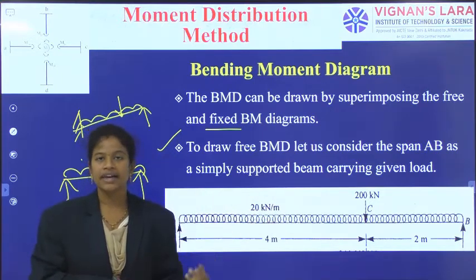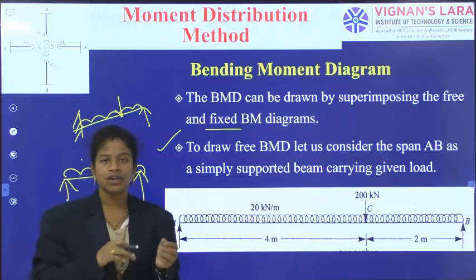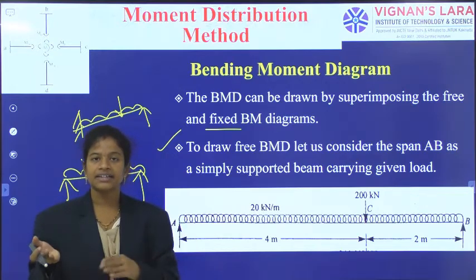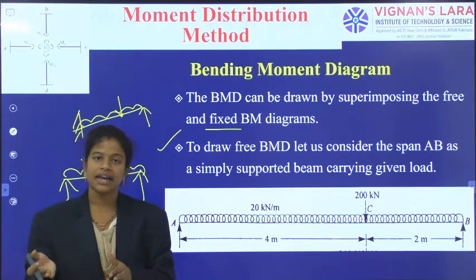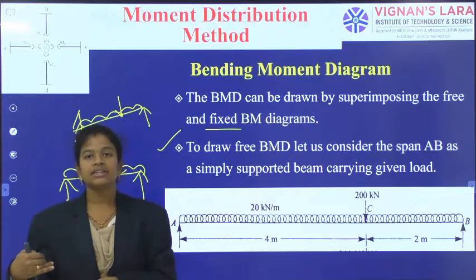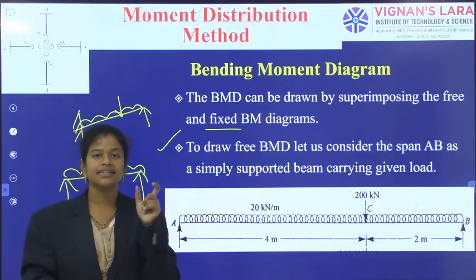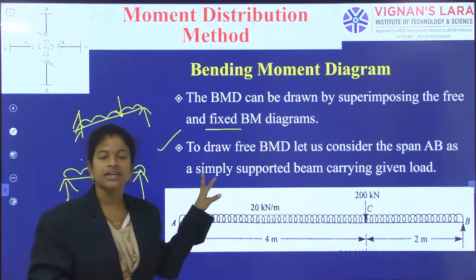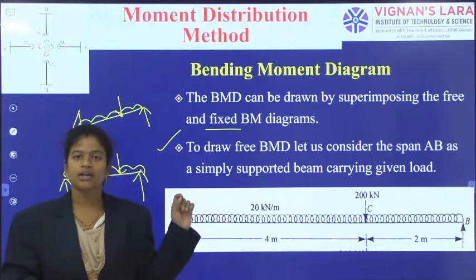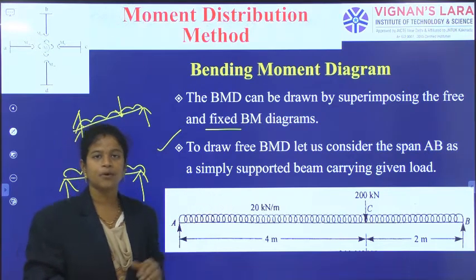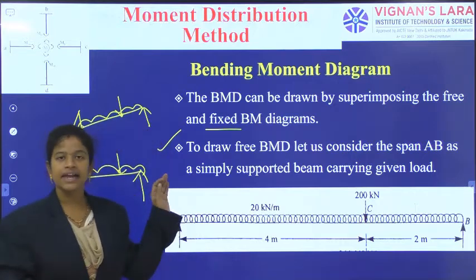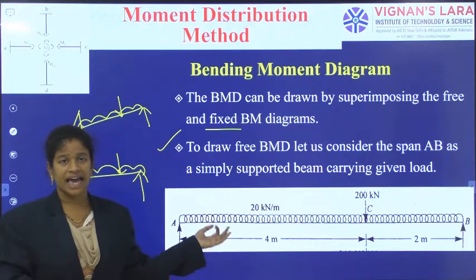In slope deflection we will calculate using slope equations, involving theta and deltas. We will calculate MAB, MBA using those equations. In some other case we will use some other method for calculating the support moments. So here I am using the moment distribution table for calculating the support moments. And after calculating the support moments, the remaining process is as it is.